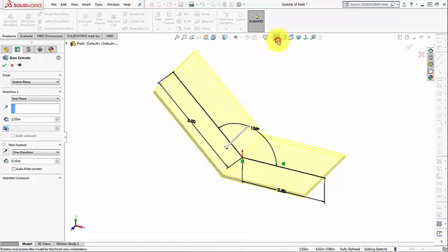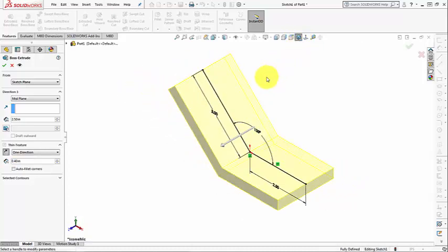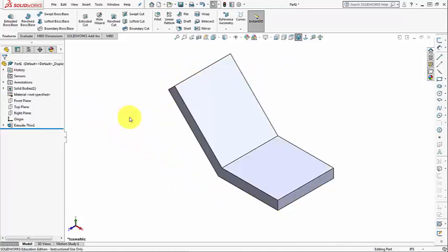If we look from the front side, first of all, I want the origin point to be on top surface. So I will reverse the direction. I will specify the thickness of the plate, and in this case it is 0.4. Okay, so 0.4, and it goes downward so that the origin point is on top face. Again, if we look from isometric view, our part should look like this. So all good here. So we click OK, and we exit from the extruded command.